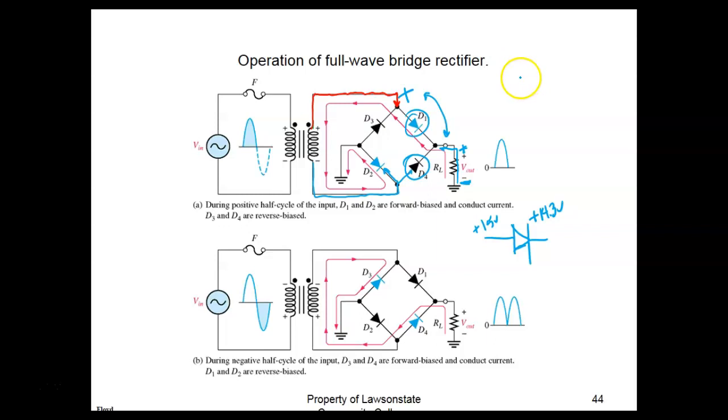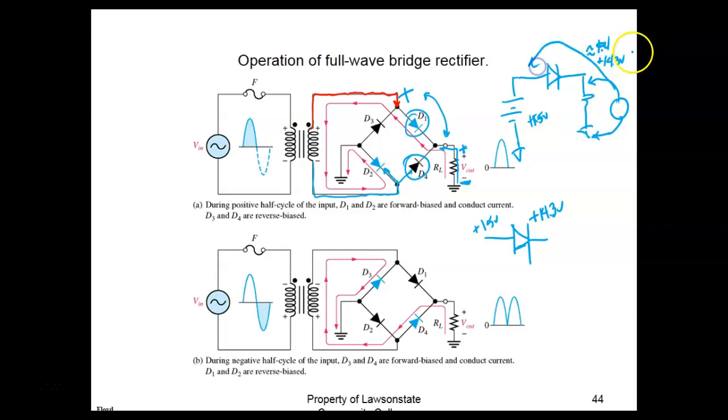This is especially true if I was to come over on this circuit right here, put my resistor right here, come over here and put my DC source, and my DC source is plus 15 volts. And I make my measurements relative to circuit common. So here's my meter right here. I'm going to put it right there, and I'd measure just about 14.3 volts plus, and when I move it right there, I would measure plus 15 volts. So odds are there's going to be something between the negative and the positive on that diode to protect it.